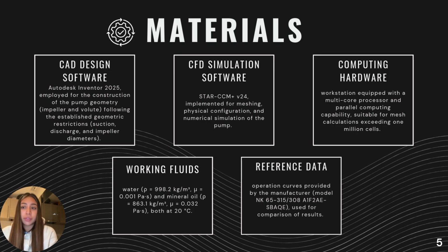Well, for the development of this CFD study, we used several key resources. First, Autodesk Inventor was employed to design the pump geometry, including the impeller and volute, following the required dimensions. Second, the CFD simulations were carried out in STAR-CCM+, where the meshing, physical setup, and numerical analysis were performed. We also used a workstation with a multi-core processor and parallel computing, which allowed us to handle meshes with more than 1 million cells.